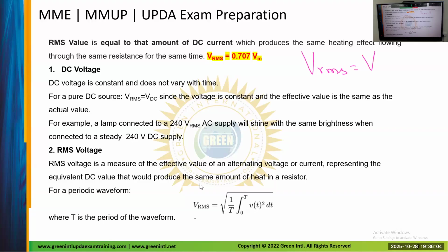Is this 240 an instantaneous voltage? On the other hand, we have a stopwatch. The stopwatch time is changing, but the voltmeter always reads 240 volts. So it is not an instantaneous voltage, because the instantaneous voltage changes from time to time, but the voltmeter reads 240 volts. So what the voltmeter reads is not an instantaneous voltage, and not a maximum voltage; it is an RMS voltage.